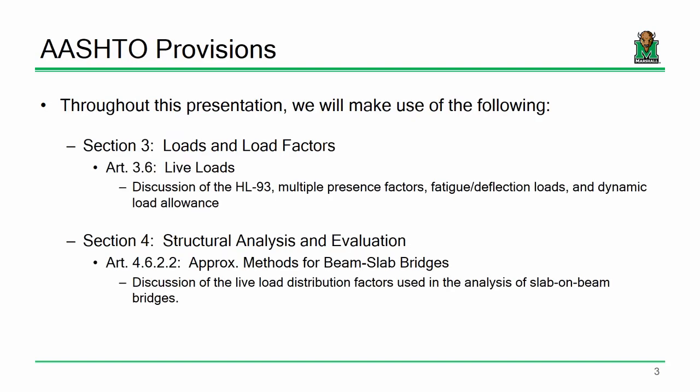So let's start off with some of our provisions in AASHTO. Some of this you had before you walked in here, and the rest of it you should have now. Okay? Now this discussion of bridge loading is going to take a while, so we're going to make use of the following. Start off with Section 3. You all have that from last time. Section 3 was where we looked at the load combos. Remember that big table of load combinations? Section 3 is also just the definition of the loads themselves.